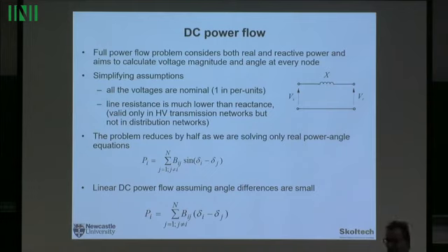But remember, once again, you neglect resistances, so you don't have transmission losses, and crucial assumptions, those angles have to be small. So for a heavily loaded network, it will not hold, because if P is high, the angle differences will be high as well.